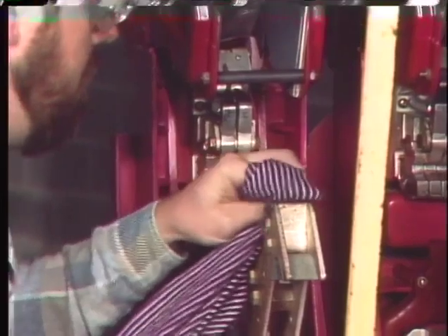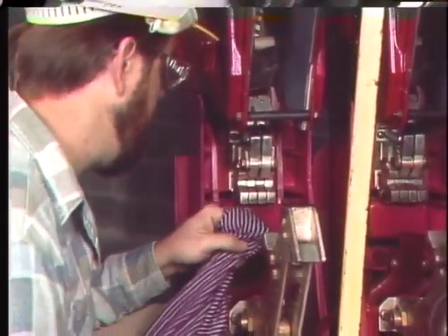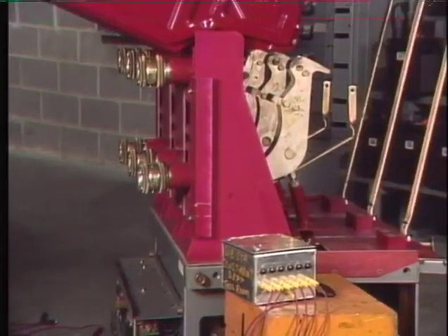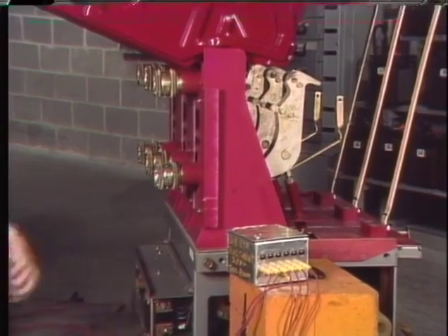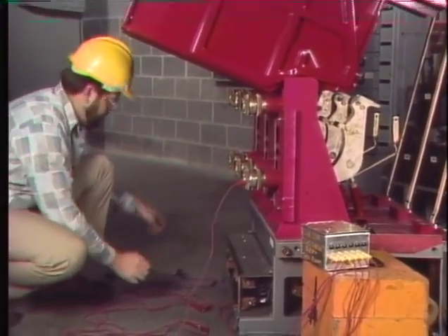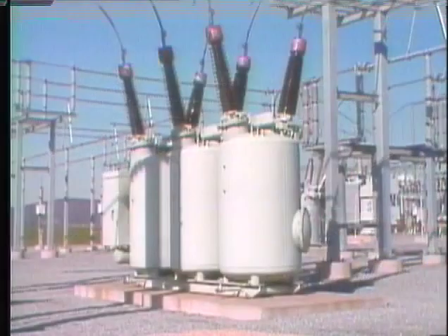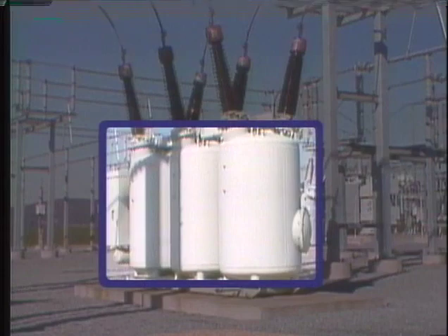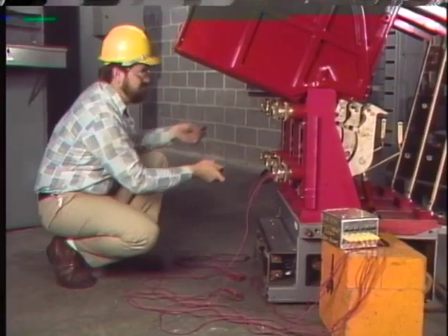Other maintenance tasks include inspecting and cleaning the contacts and checking the contact adjustments. One adjustment that is checked is initial contact engagement. This is a check to see if the arcing contacts for all three phases of a breaker touch at about the same time. For some breakers, the contacts for each phase may be in separate tanks, and initial contact engagement is often checked using a continuity device.